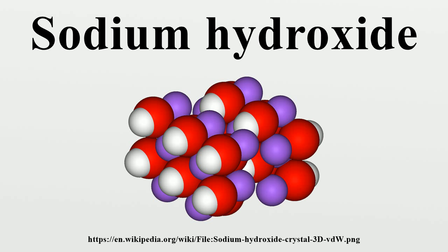Production. Sodium hydroxide is industrially produced as a 50% solution by variations of the electrolytic chlor-alkali process. Chlorine gas is also produced in this process. Solid sodium hydroxide is obtained from this solution by the evaporation of water. Solid sodium hydroxide is most commonly sold as flakes, prills, and cast blocks. In 2004, world production was estimated at 60 million dry metric tons of sodium hydroxide, and demand was estimated at 51 million tons. In 1998, total world production was around 45 million tons.